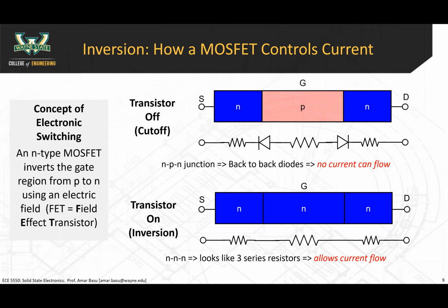So the physical way to actually change doping involves putting the semiconductor in a furnace with a process gas, and it takes several hours to do doping. So if we want to turn a switch on and off and it took several hours to do that, obviously that would not be a practical way. But the reason I asked the question is just to remind everyone, okay, so far the only tool that we have in our toolbox to change P-type to N-type is doping, and that's super slow.